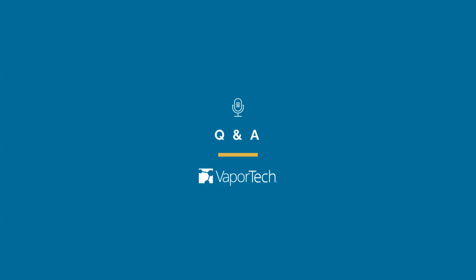So that's more or less the advantage of cathodic arc with respect to sputtering. If you compare our specific process to other manufacturers that sell cathodic arc, we are very different in the sense that our target is a central target inside the chamber, which is spraying material in all directions at the same time. That's not the right technical term, but it gives you a good idea. So you have really good coverage.